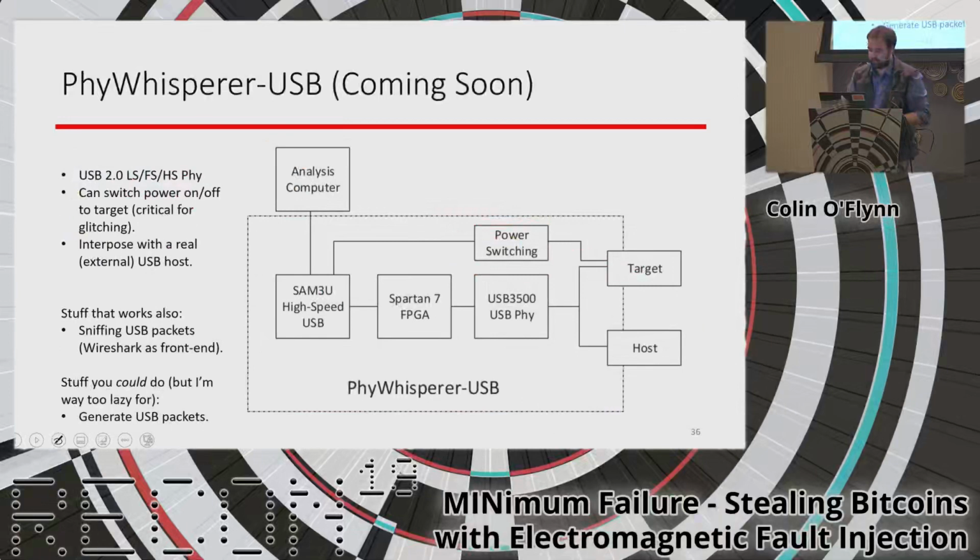The idea of this is not to inject packets. Theoretically, it can do some of this, but there are better tools for this. If you're using something like FaceDancer or now GreatFET, that's really designed to do the type of USB fuzzing. This is really looking at physical layer effects and physical layer triggering that we can get out of having a USB PHY and an FPGA together.